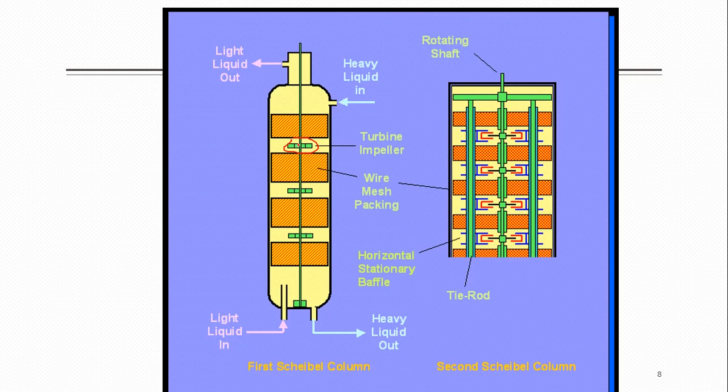So in order to avoid this problem, we have introduced some baffles, and they were called internal and external baffles. So here you can see they have introduced some tie rods inside this assembly, and with the help of these they have connected some baffles. Baffles, you know, are plates which can stop the liquid from escaping through some easy path. So overall these are internal ones. Here maybe he has mentioned, but in the next slide, okay, I will show you. These are internal ones.